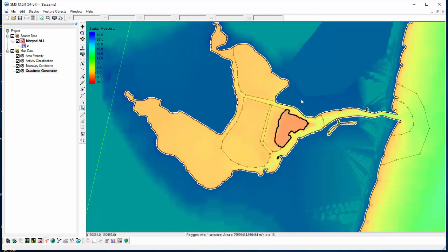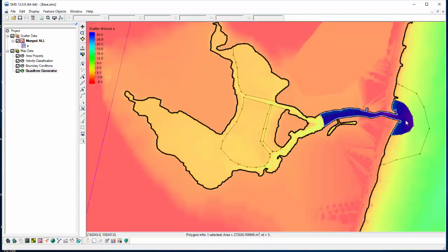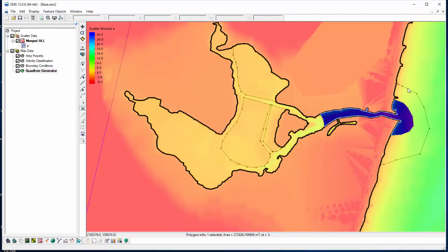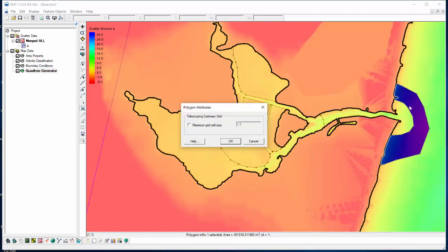That should be fine. So what we would do is for the various areas, this one I said I wanted to have be 5 meters. So I can double click here, check the box and say this is going to be 5 meters. And this next one, since it's right next to this one, shouldn't be more than double that amount. That's just the way resolution works.